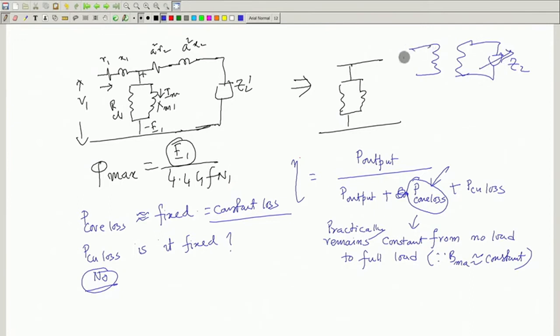Here it is V1, f1. Open circuit, Z2 infinity, switch is open. Then I will load it by decreasing this Z2 and your current will go on increasing, and the ratio of the currents is approximately the turns ratio. Therefore, the level of current will go on changing as you change the load on the secondary of the transformer.